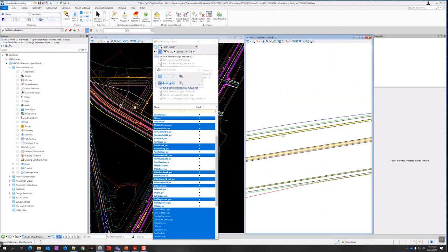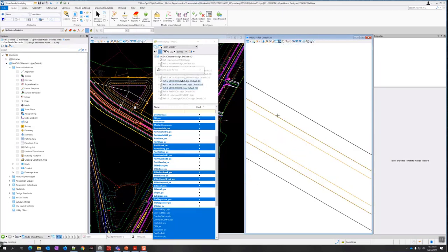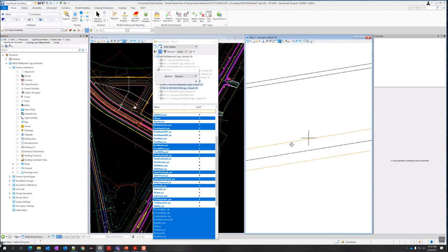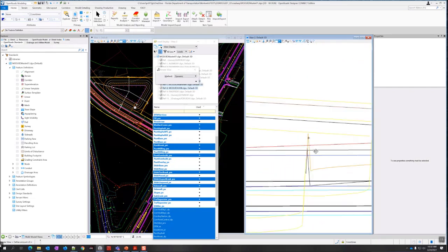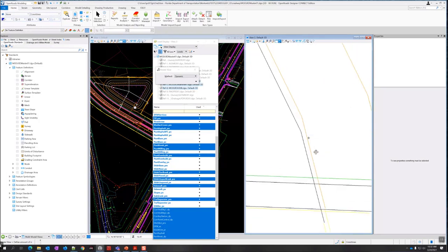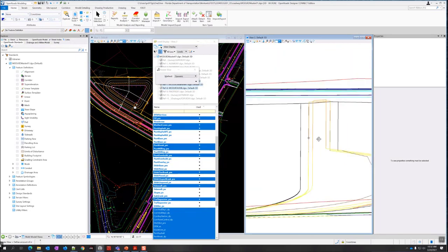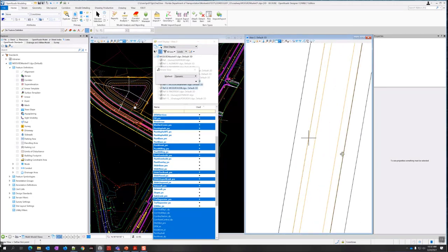Sometimes you can rotate it, to make sure that things aren't stacked. If you change it to top view and things go away, then they might be stacked. If I zoom in here, this is right next to it, so it's probably okay. This is just the traffic separator and then the pavement asphalt, which is right next to it. If I go back to an isometric view, or if I rotate the view, I can see how that moves around. It's a lot harder to see when you're just looking at lines what things are doing. So that's the top of the pavement next to the traffic separator there, and we've got one here on the other side as well.